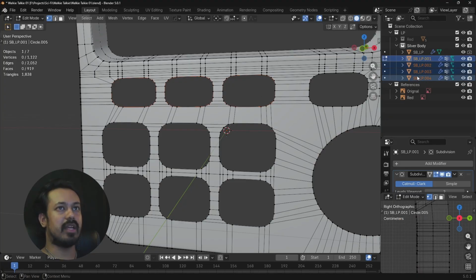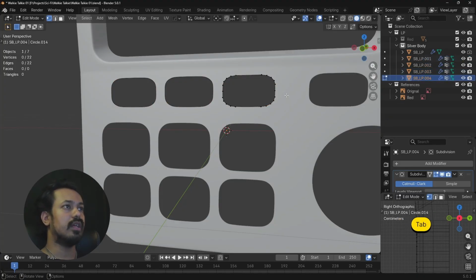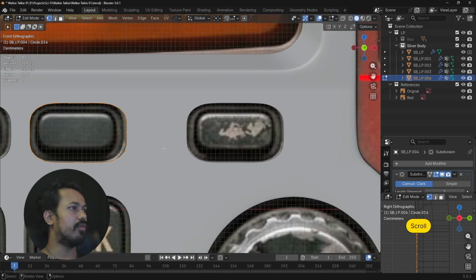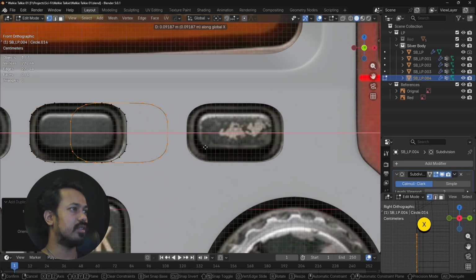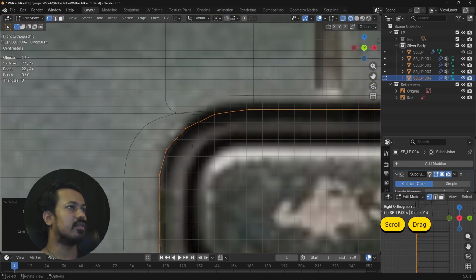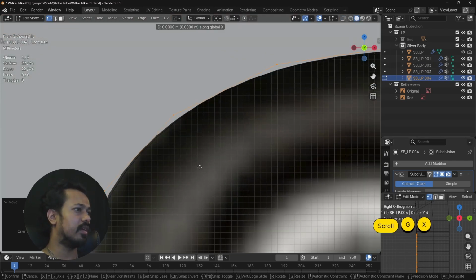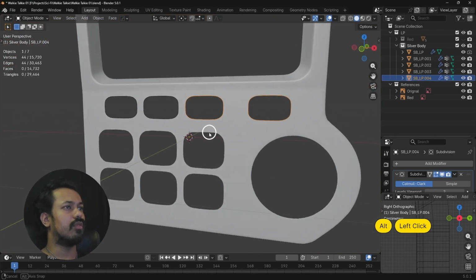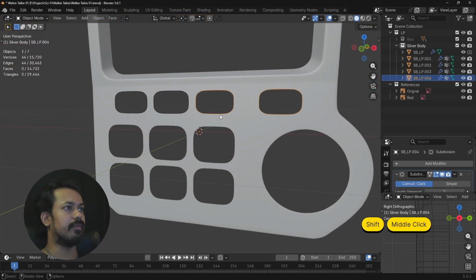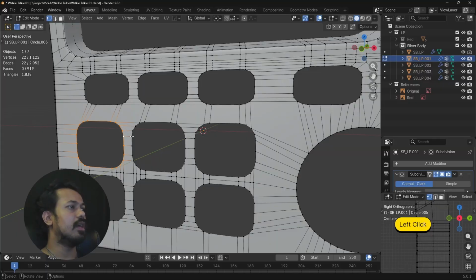and here is the magic that we want to look for. When it comes to this, all we have to do is Shift D, G X, and make sure that it just aligns as much as you can to the same exact vertices that we got. There it is. And now we have solved the direct issue that we had with this as well. The same thing here. And you might be wondering why I'm not just doing it like this, because it's going to select the edges also, and I don't want to do that at the moment.